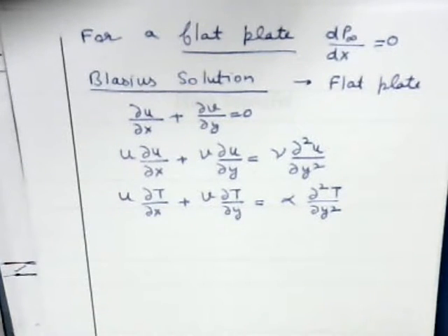But the problem is Navier-Stokes equations cannot be solved for an external flow without using computers. So we modify those equations with boundary layer approximations, and we get boundary layer equations, and those equations can be solved. We are solving those equations for flow over a flat plate. Our objective, for this particular situation of laminar flow, is to determine the convection coefficient.